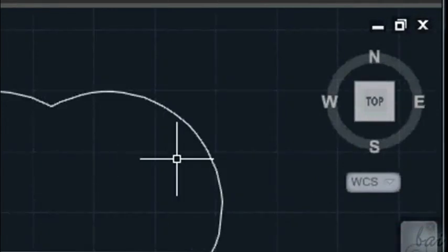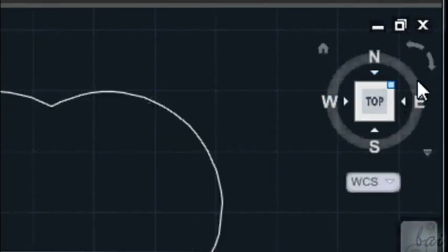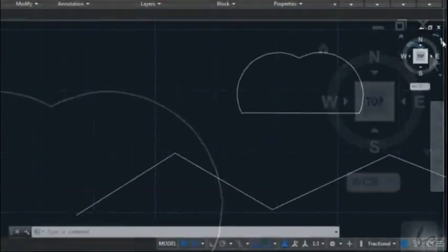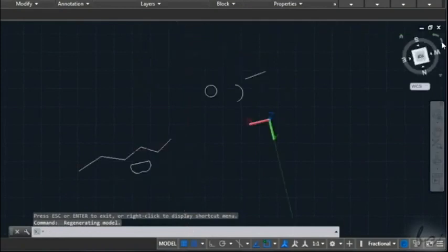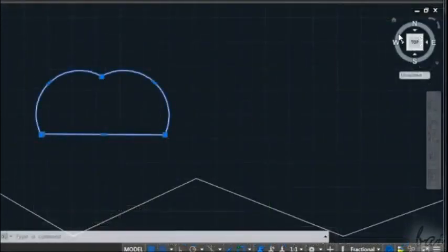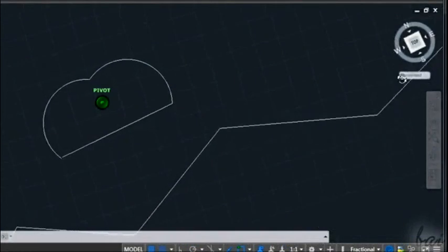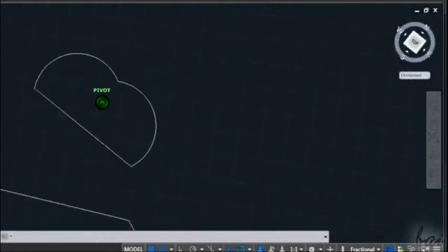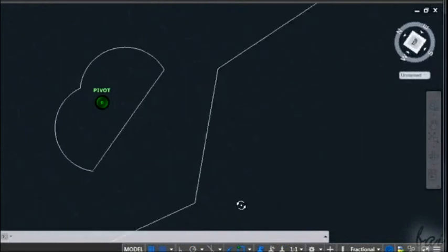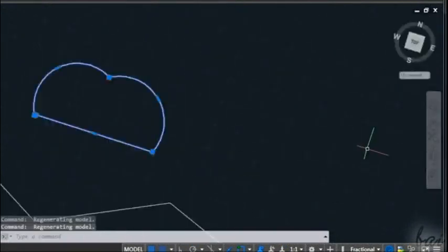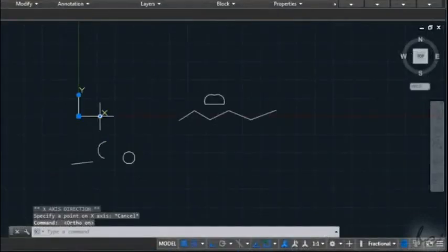Even more, you can use the 3D View cube in the top right corner of your workspace. As long as you work in 2D, just the face top is needed. This means to see your project from up to down. In this case, you can rotate your project using the hidden arrows on the right or dragging the circle around the top face. But the workspace grid is the cube on the center, and this one follows the Cartesian axis fixed. This can be edited as a normal object.